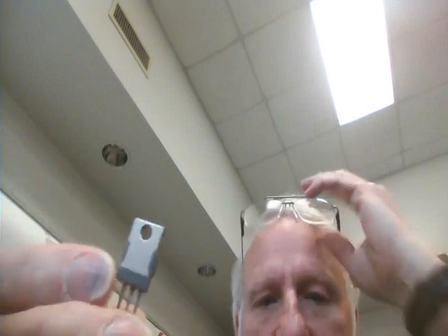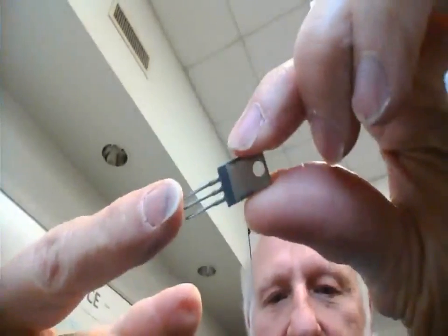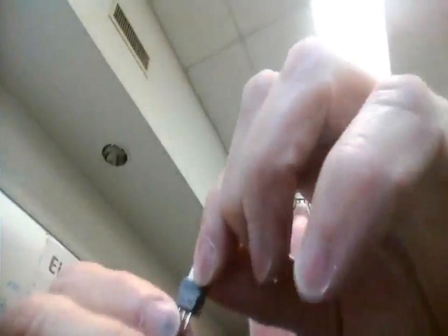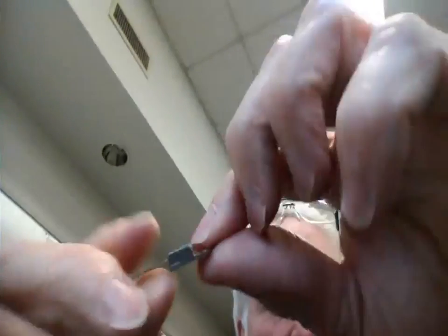Now it has 3 leads. It has 3 leads on it. But if I took an ohm meter and measured between one of these leads, one of them would measure continuity to this big nice metal tab that's on it. And I just identified the collector. So the collector is going to be connected to these tabs, because what we're trying to do is dissipate the heat. And how much heat you can dissipate is directly proportional to how much surface area you expose that to, right? You understand?